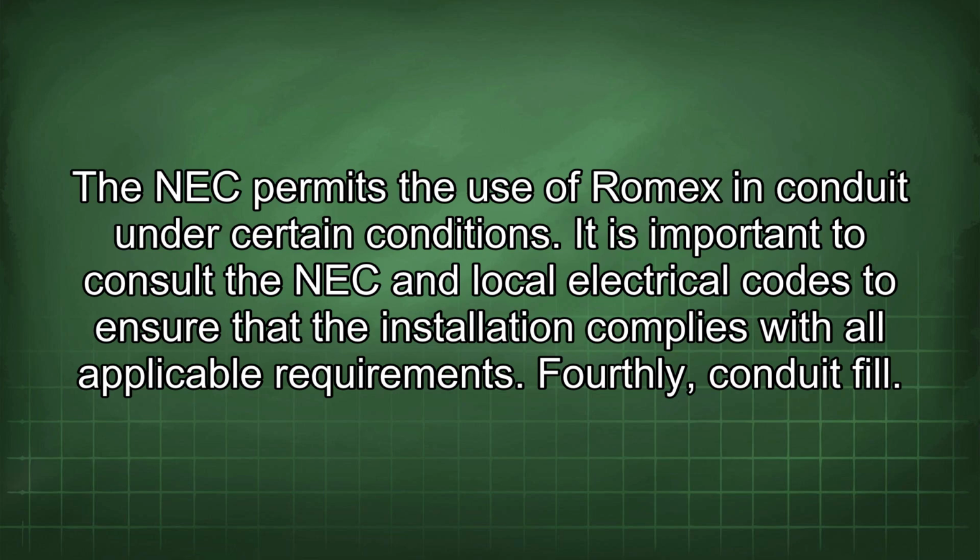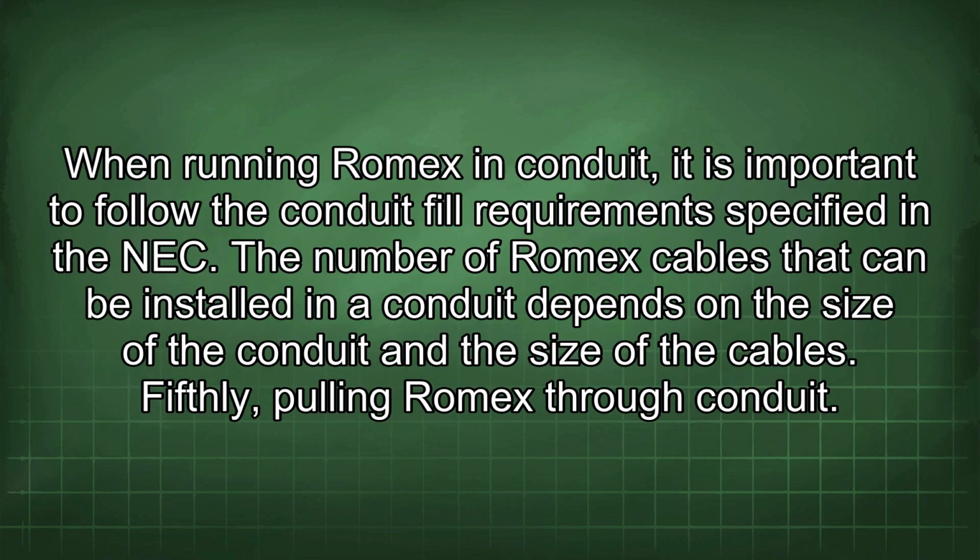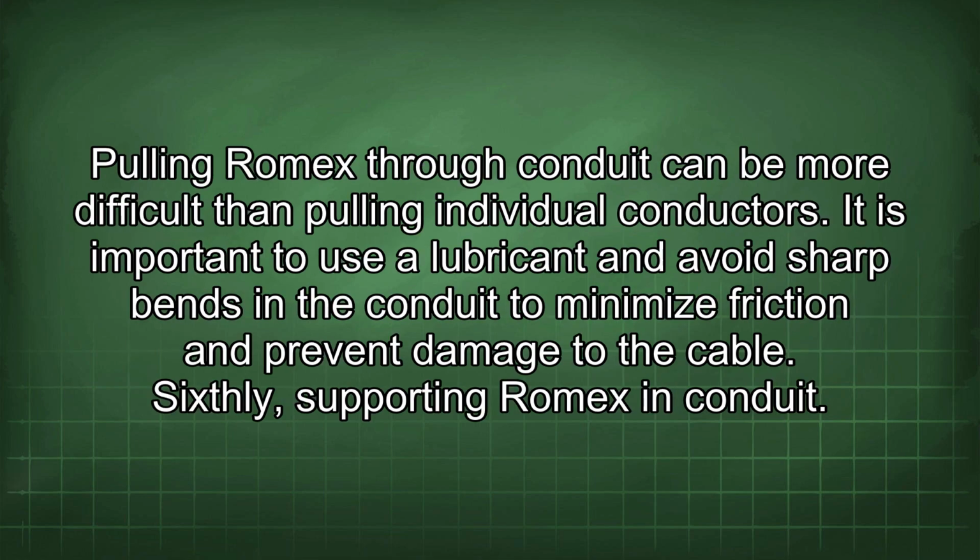Fourthly, conduit fill. When running Romex in conduit, it is important to follow the conduit fill requirements specified in the NEC. The number of Romex cables that can be installed in a conduit depends on the size of the conduit and the size of the cables. Fifthly, pulling Romex through conduit. Pulling Romex through conduit can be more difficult than pulling individual conductors. It is important to use a lubricant and avoid sharp bends in the conduit to minimize friction and prevent damage to the cable.